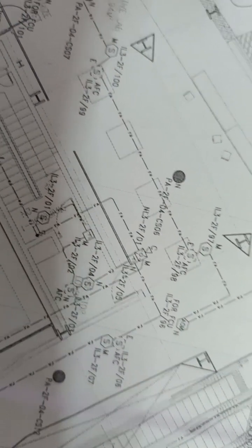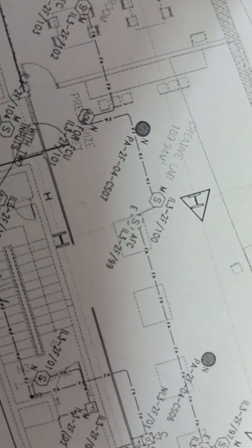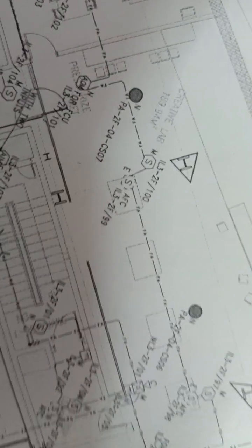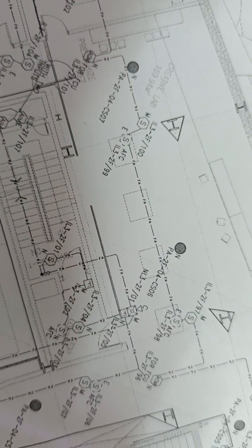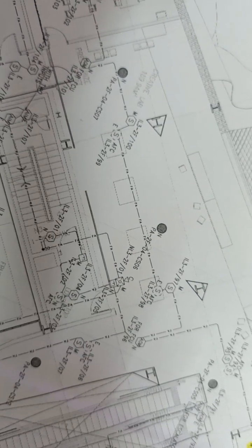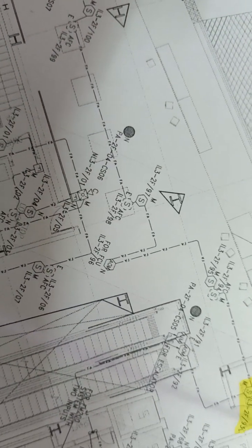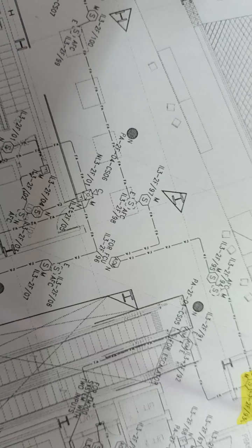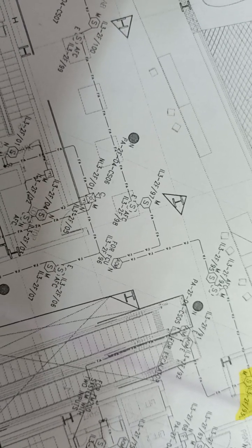Actually in this drawing, here you can see there is a gap between this smoke detector and this smoke detector, this 100. So in between there is a gap of 9 meter. So within the range of 9 meter you can install the smoke detector. Within this range only the detector can sense the temperature increase or fire. So it will give the signal to the fire alarm control panel.